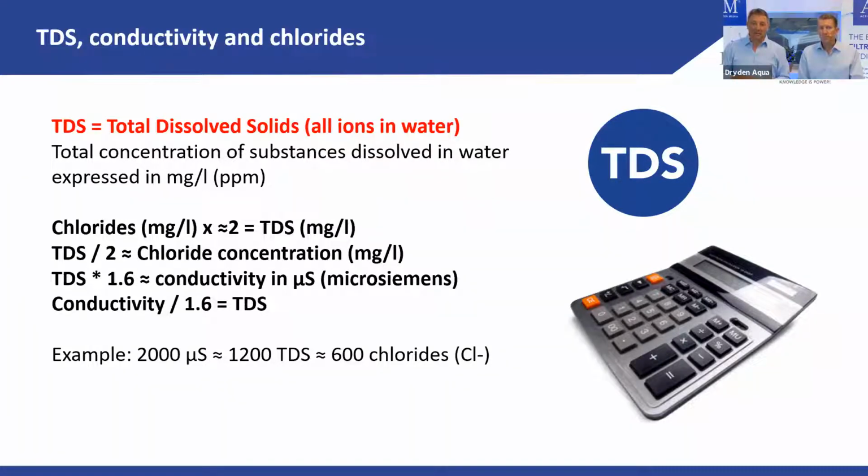Now, it's quite difficult if you want to find out how much TDS you have in the water. It's a difficult job to go to the water and count the different ions. Chlorides you can measure with these droplets. You take water and add the droplets, and when it changes the color of the water, you find it out. But the easiest way is to measure conductivity.